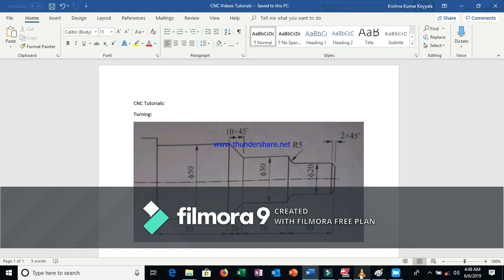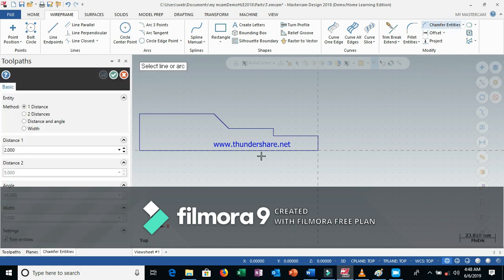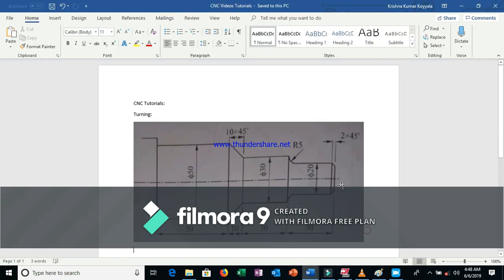Yes, now select one chamfer. Select chamfer. Yes. So how much length? 2. First we will do this one, the beginning you can say, this chamfer.